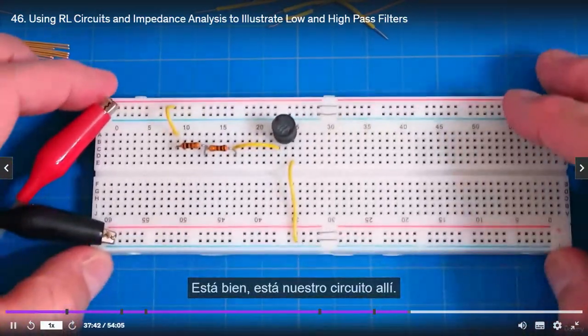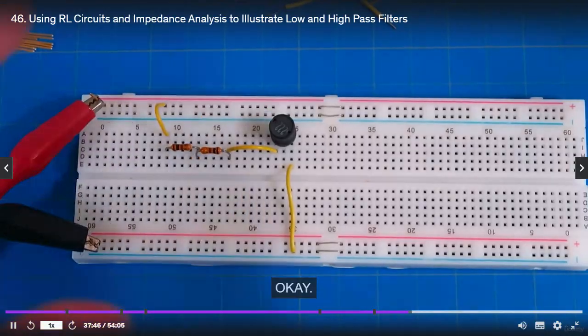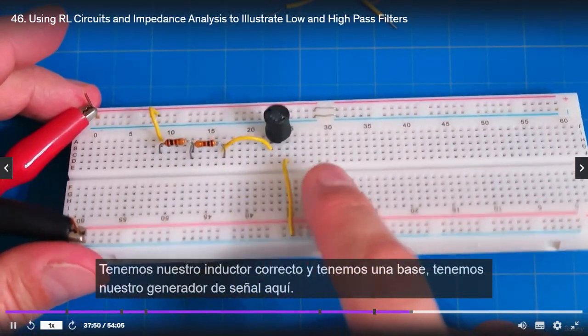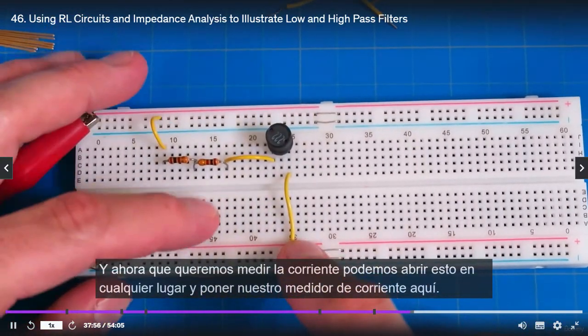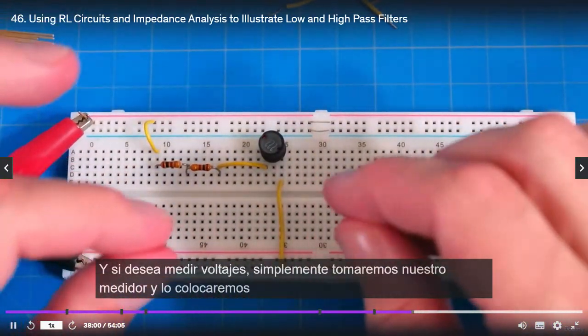So there's our circuit right there. Let's zoom in just a bit. There's our circuit right there. So we have our resistor, we have our inductor, we got our ground, and we got our signal generator here. And if we want to measure current, we can open this up anywhere and put our current meter in here, right?